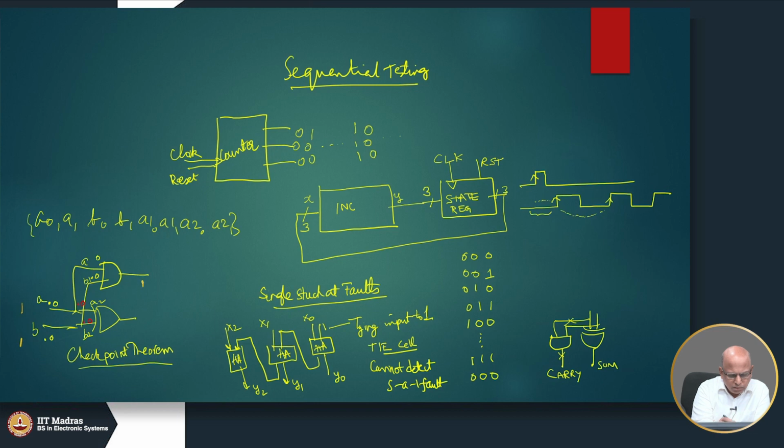So, that is supposed to give me a 1 here and a 0 here. So, what are the circumstances under which this 1 is likely to change? Which one of these faults will cause a 1 on this line to become 0? I suppose B1 stuck at 0 will be caught, because if B1 is stuck at 0, the output will change.